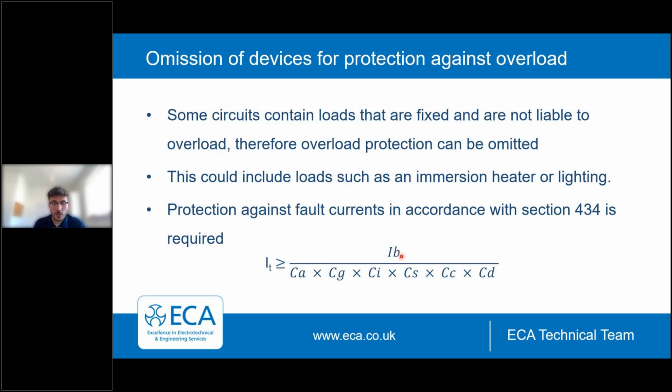However, there's one subtle change in that when we protect a circuit against overload, when designing the circuit and selecting the cable size, we often do In divided by applicable rating factors. But where we're not protecting against overload, it would be the design current divided by any applicable rating factor.